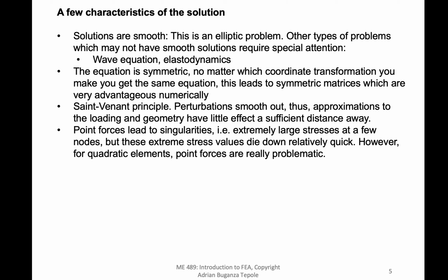Another characteristic of our problem is that because it's an elliptic problem, and because we have just the second derivative, the equations are symmetric. And actually, when you discretize with the method that we described, which is we use the same shape functions for both the solution and for the weighting functions, then you get a symmetric system of equations.